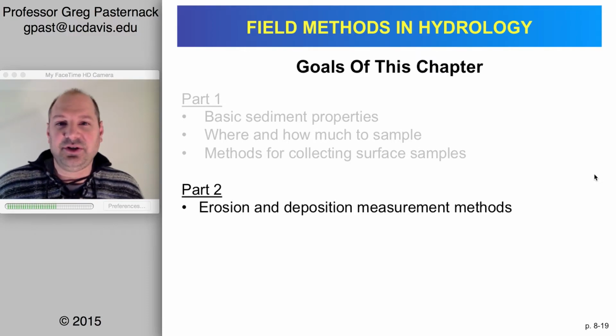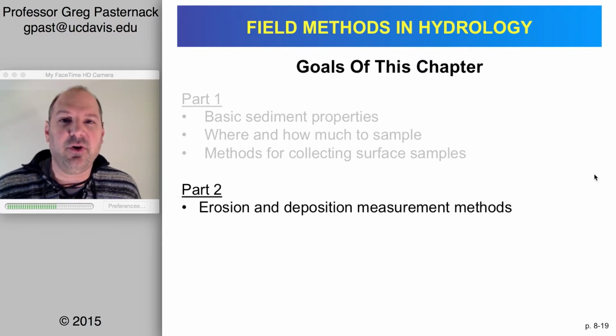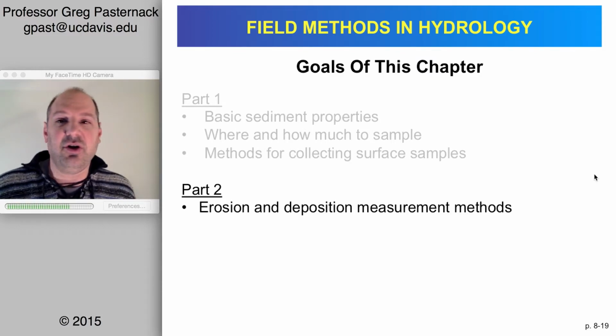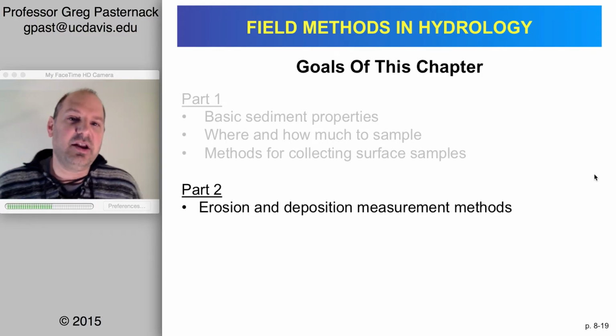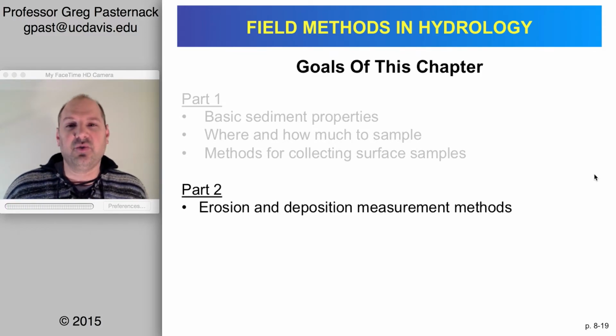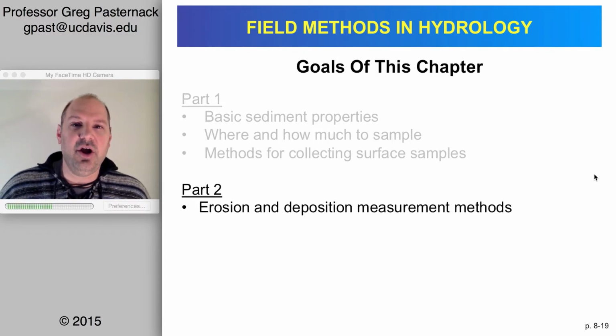Movement of sediment, of course, plays a role in changing the volume of space available for water storage. When sediment moves, it changes the hydraulic conductivity of the material. So, if you have an erosion of material and then deposition of fresh material, the deposited material tends to be less compacted and have higher hydraulic conductivity rates, and it can change the habitats that are there. So there's a lot of reasons directly for hydrology as well as for allied sciences as to why we want to know about deposition and erosion of material.